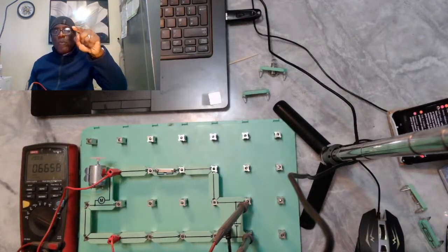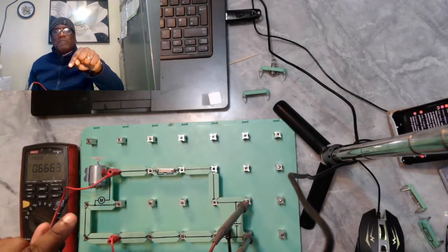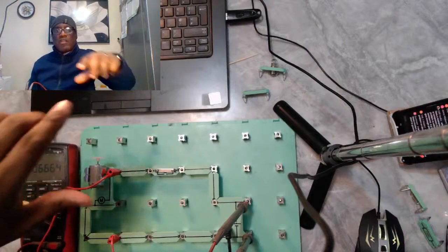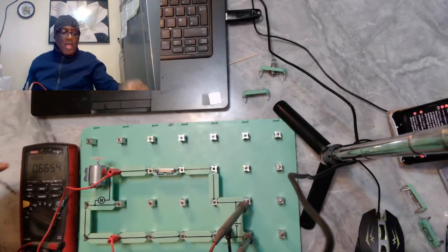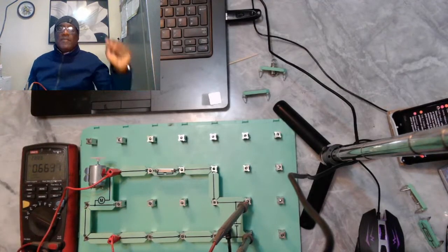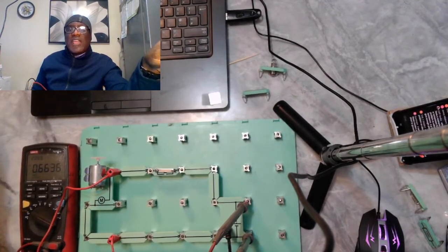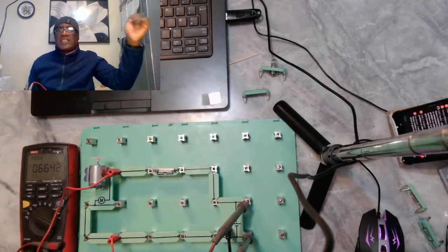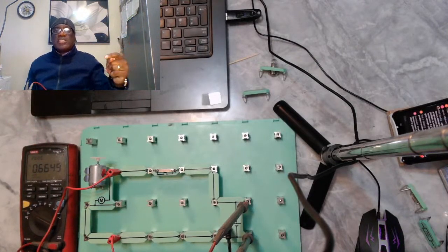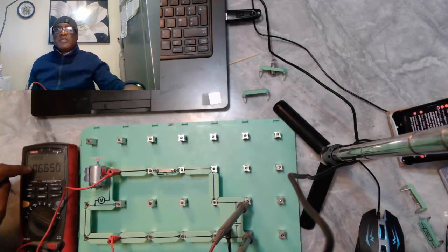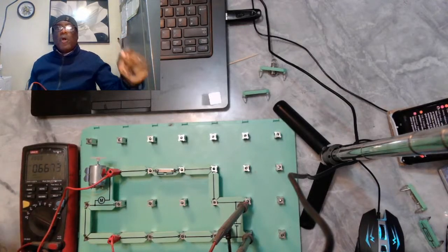Once you get to the one that is shorted to ground, the moment you disconnect it, boom, your 5 volts comes straight on the meter. Then you know that's the devil, and you deal with it. The moment you disconnect it, your short to ground is gone, 5 volts comes back again. You are good to go.